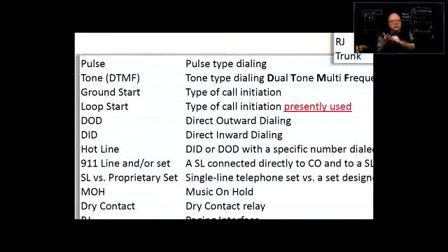Now, originally, when the dial was introduced, there was no tone dialing. It would be pulse dialing. So you would have the rotary dialer. You would bring whatever the number to the finger stop, and you release, and this thing would come back, and how long it takes to come back would produce certain types of pulses, which would be just interrupting and connecting the telephone line. And the circuitry in the CO, central office, would sense those pulses, and those pulses would represent a number.